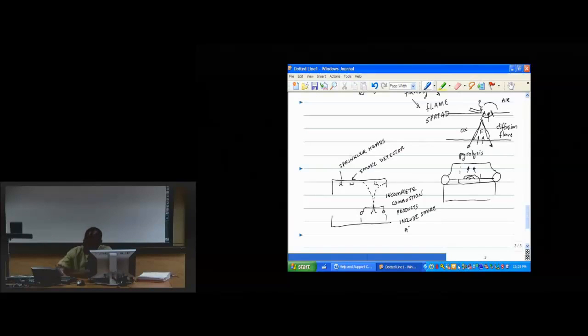The sprinkler heads are thermal devices. They're thermally fused devices, so there has to be a hot enough plume, a hot enough gas temperature at the ceiling level to activate this. And there's a physical process called a ceiling jet that runs across the ceiling.